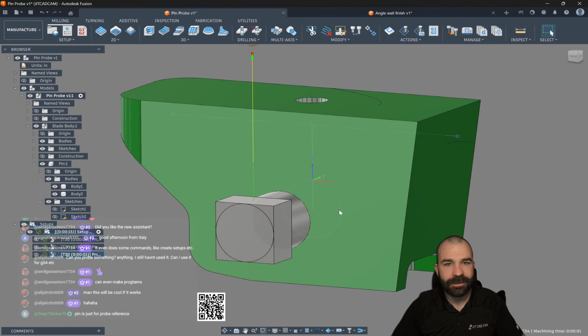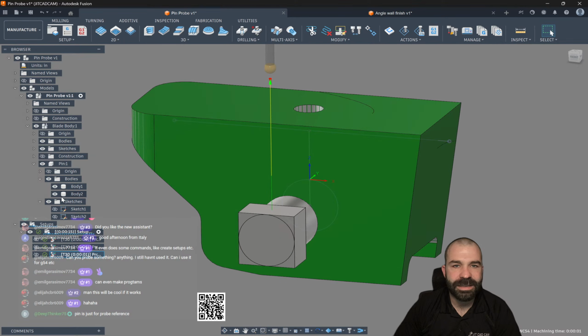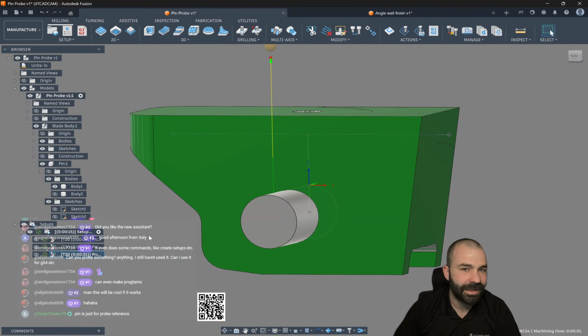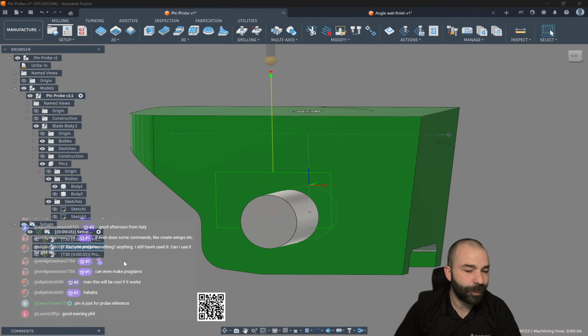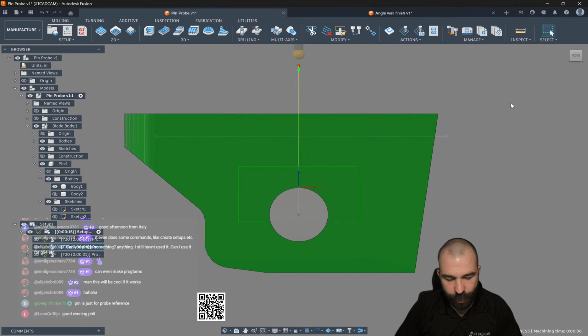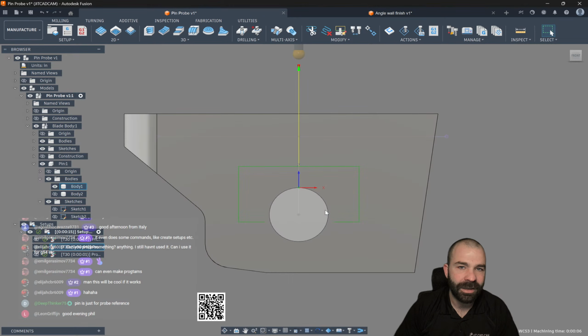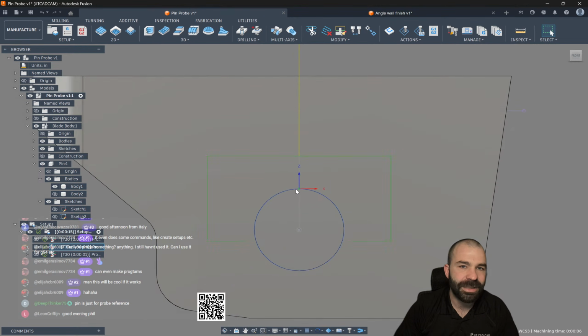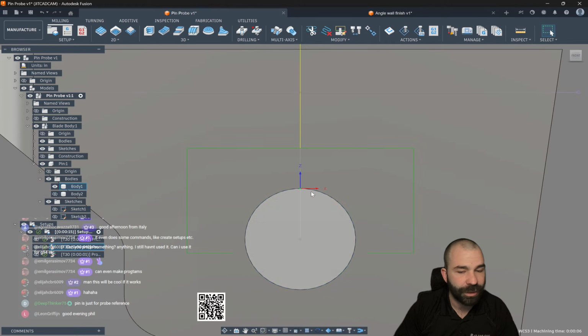So with that, we are now picking up Z technically off the top of the pin. As well, pro tip here for a lot of you guys, I would highly recommend that if you are probing in the x-axis fashion on something round, do the x-axis before the Z, because if your Z was over here to the left, you would be low. If you were over here to the right, you would also be low. You want to try to get on top of that cylinder as best you can.